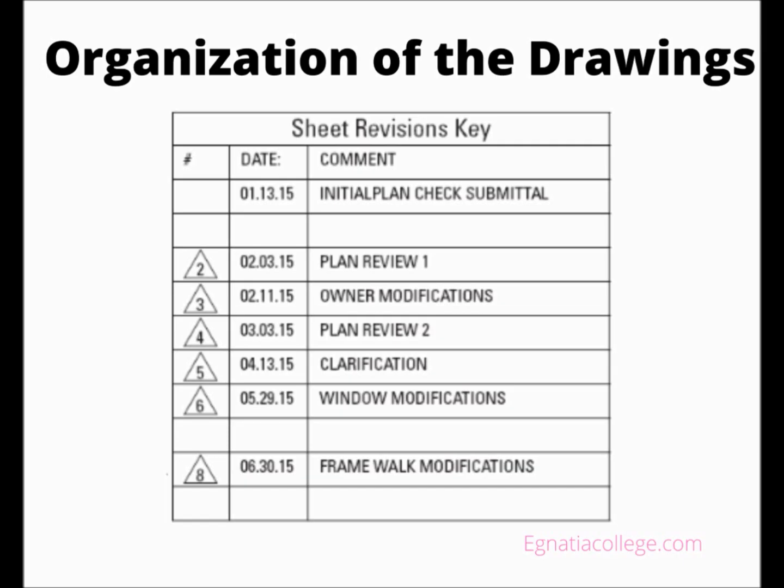A small, numbered triangle matches numbered triangles found in the title block of the drawing. The same technique, enclosing in a scalloped line or cloud, is used for revisions to the drawings themselves. Some other useful information shown on the cover sheet for the urban courts are: symbol legend. Explains the symbols that are used for sections, elevations, keynotes, explained later, and revisions.